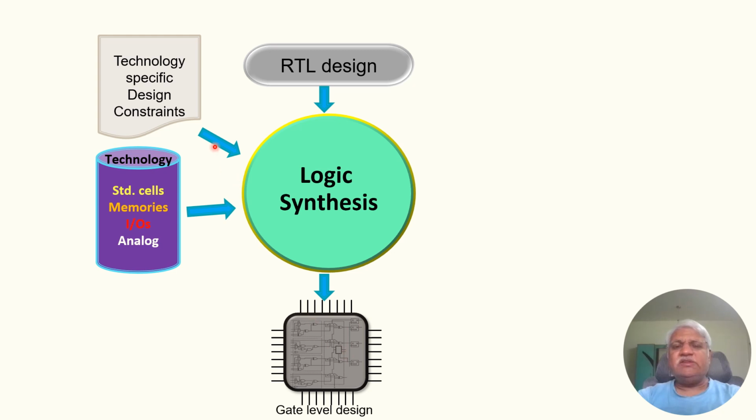These technology specific gates, from so and so technology, say either 28 nanometer technology or 5 nanometer technology or 2 nanometer, all that will be instantiated. Corresponding logic gates will be instantiated because this is the input supplied. So the design is converted based on these technology gates, say whether inverter or NAND gate or flip-flop.